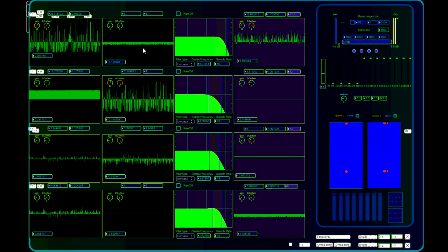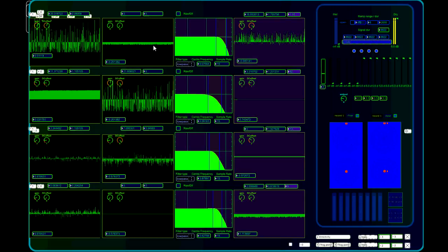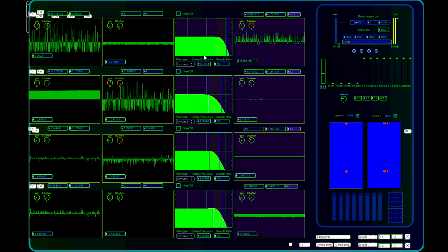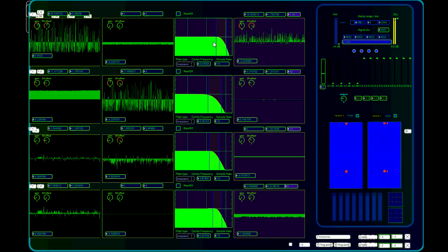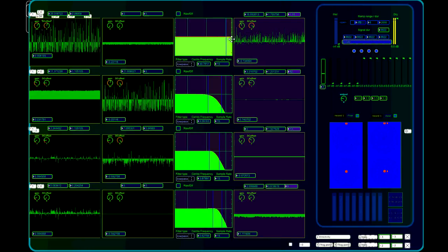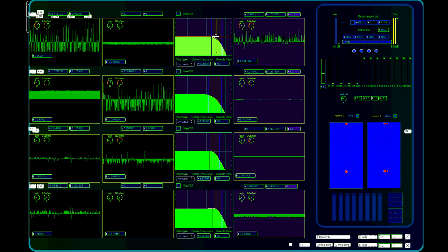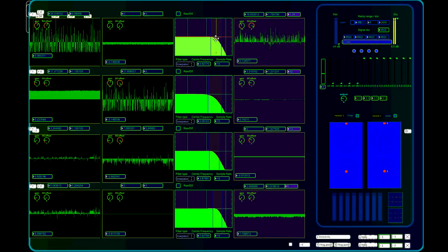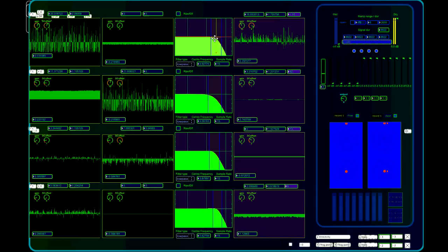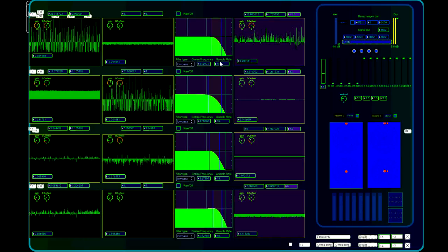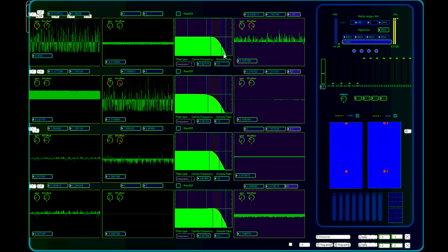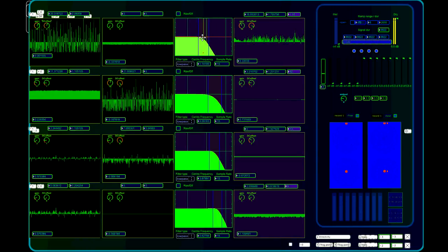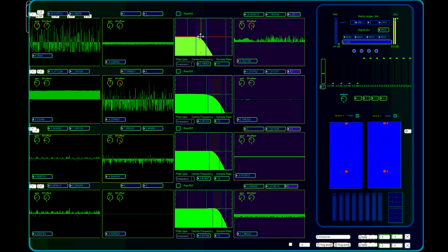in plant electrophysiology. This here is a filter. So basically you can see where exactly the filter's filtering. There's a center frequency there, and you can filter out noise that you don't want, or focus in on one particular frequency that you do want. So if I filter out some of the noise by turning this filter down, you can see that I'm getting a much purer signal